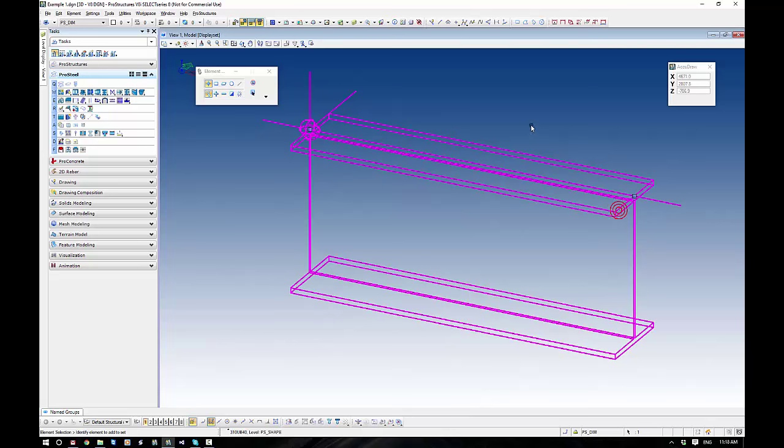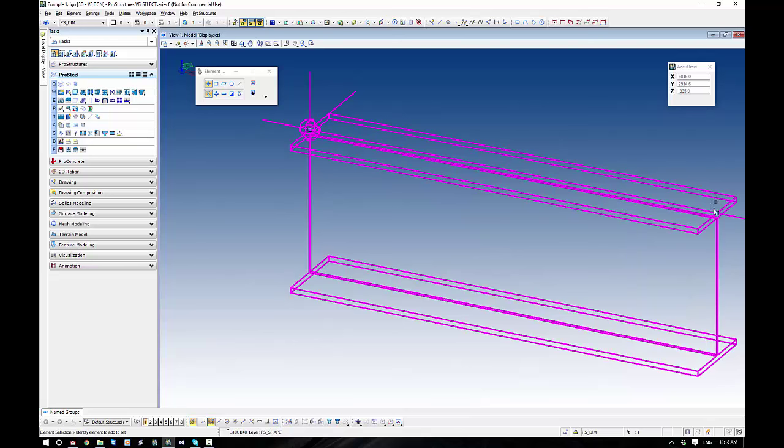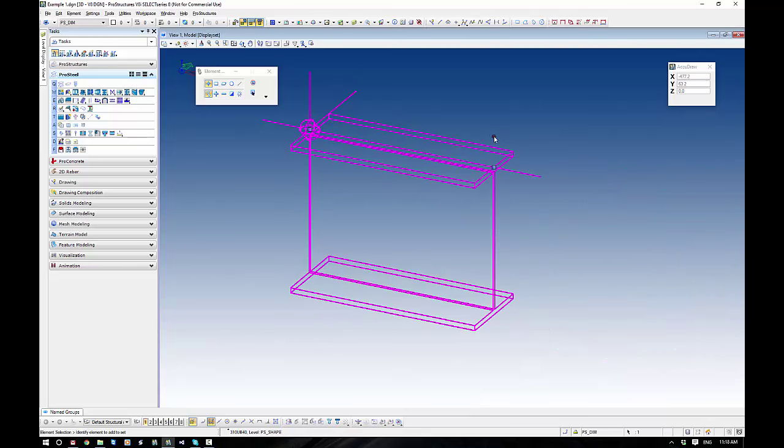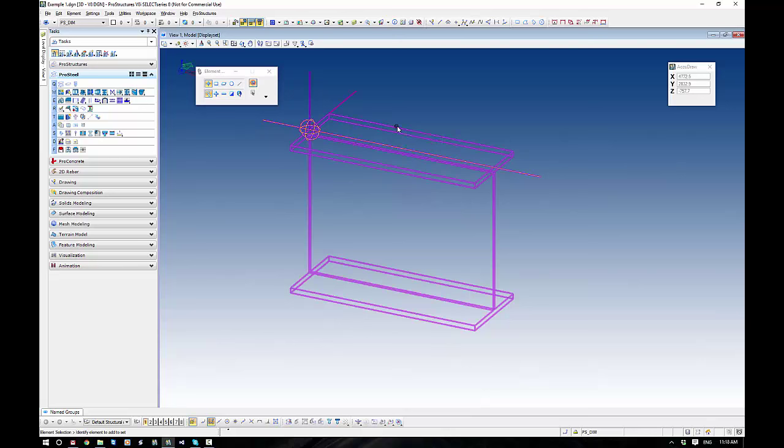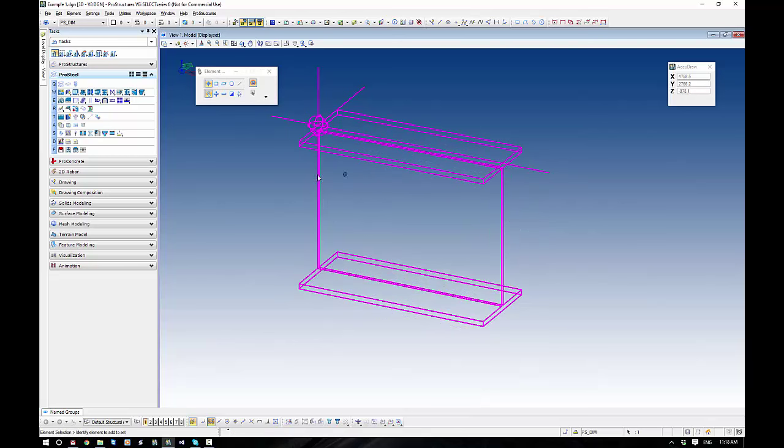Absolutely critical to how it tells us how every object has been created. You can see that we have these little grips here, and we can just pull it. It will only ever go in the direction it has been initially created in. One of the things that a few people get stuck with is they tick this disable handle by accident. And you can see here, once I hover over the object, there is no handle. It's just going to move.